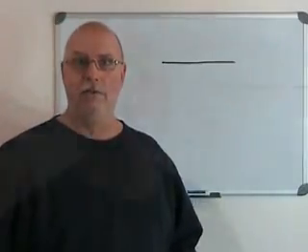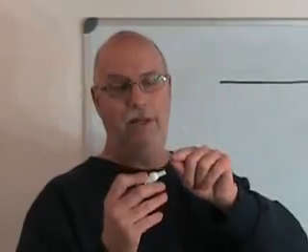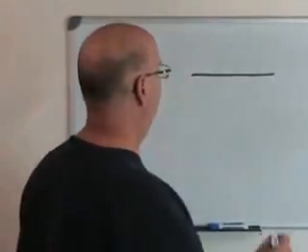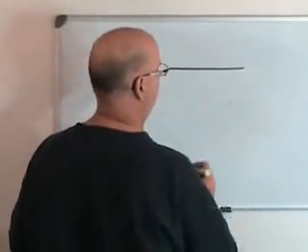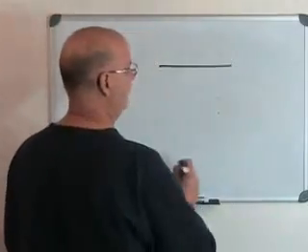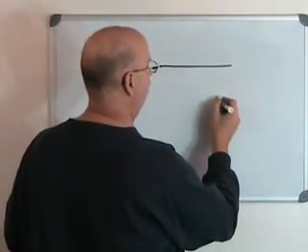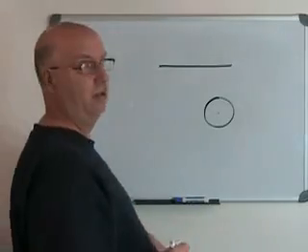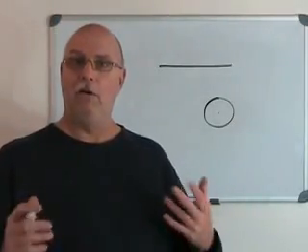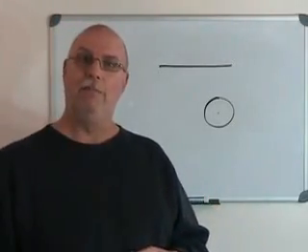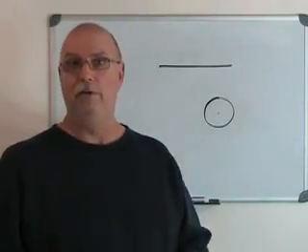Just that simple. For the circle, I'm going to use the same approach of avoiding looking at the tip of my pencil. I'm going to mark the start point, I'm going to mark the center point, I'm going to position myself, and then I'm going to draw my circle. Freehand, quickly, without looking at the tip of the pencil. It's the best way to do it.